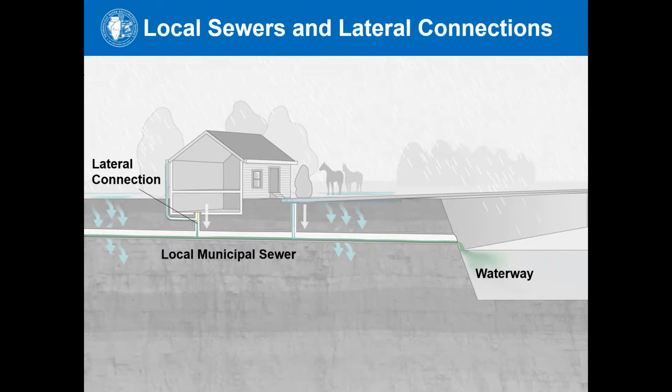By doing this, the city and surrounding communities could begin building below grade sewers, like you can see here. These were built before wastewater treatment existed, so they were designed to take stormwater and sanitary sewage and send it directly into the surrounding rivers. When these sewers were built, they carried a lot less water than they would today, simply because there was more open area at that time. There was much smaller houses and buildings, so the runoff from their roofs and downspouts was significantly less. And there was also much less intense storms than what we've been seeing, especially over the last few years in the area.